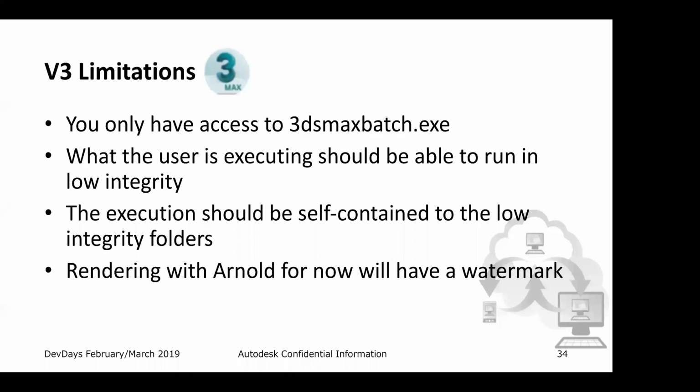So if you install just AutoCAD and the object enablers, you can load those drawings, but you cannot access the APIs or the specific features for those products. You can do this on the desktop because most likely you have the other products installed, and that's the difference here.